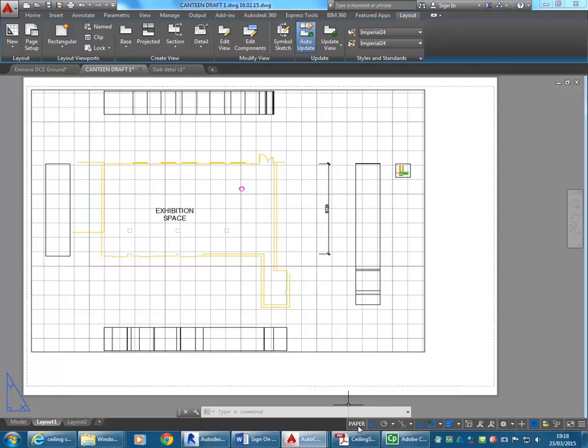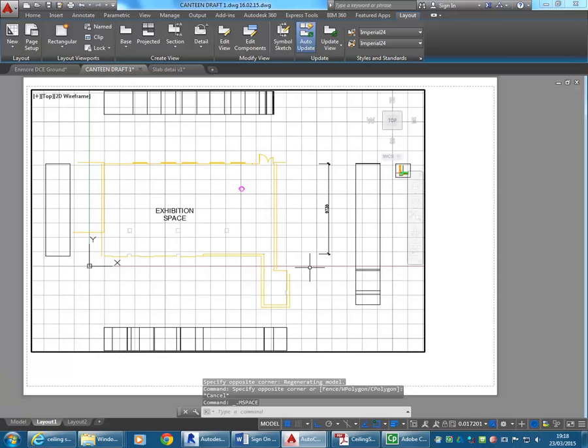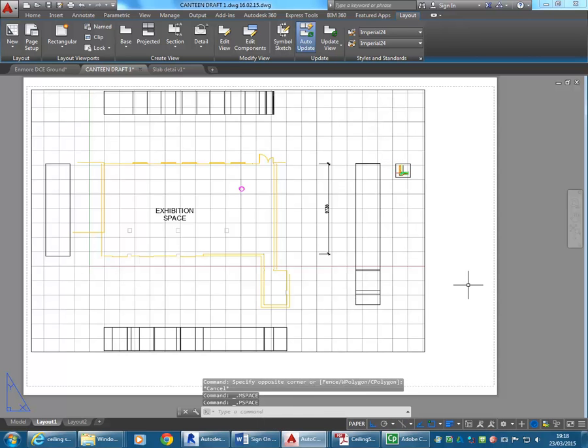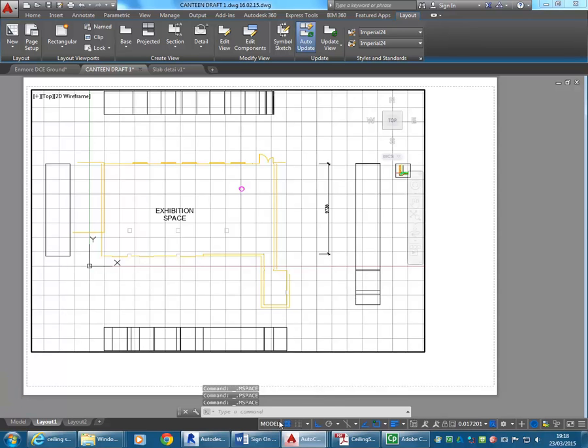And so the next thing is to set model space by choosing the button that says paper. You might have been shown that you can double click as well. That's another way. So double clicking on the viewport takes you into it, and you can see there it now says model. Double click on the page and that takes you back to paper, and you can see it says paper there. So model and paper are your two modes, or model space and paper space.